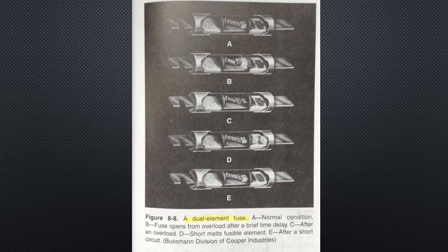A time delay fuse or time delay feature is inherent in dual element fuses. However, not all time delay fuses are dual element. The main feature of time delay fuses, regardless of number of elements, is that they allow for momentary overloads.